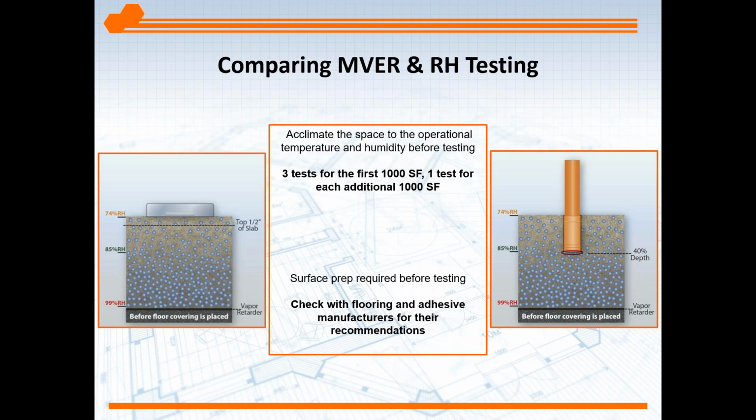But what happens when we install flooring, when it's impervious, impenetrable, impermeable? Now the moisture in the air is irrelevant. Now that moisture that's sitting in the concrete at the bottom wants to equilibrate with the moisture at the top. So all that moisture in the bottom that we didn't know about, because calcium chloride only measures near the surface, is going to want to move to the top, distribute evenly, and all that moisture at the surface is going to push off your flooring, create alkaline deposits, etc., etc.